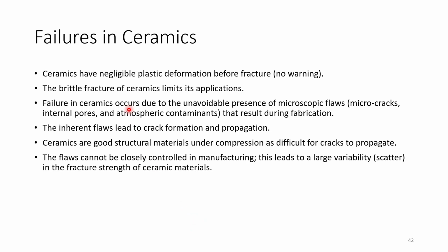Next is failures in ceramics. Ceramics have negligible plastic deformation before fracture and they give no warning. So they are very brittle in nature, that's why they show catastrophic failure. The brittle fracture of ceramics limits their applications.